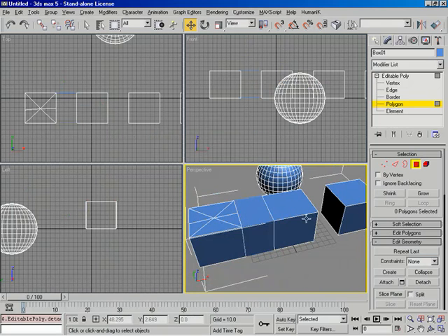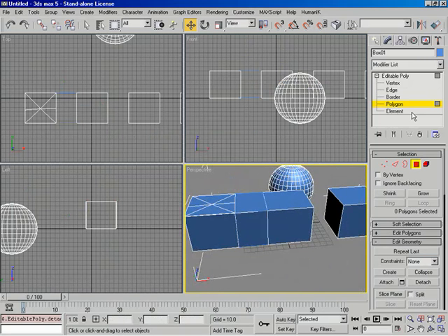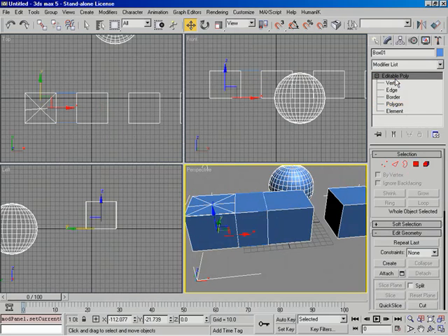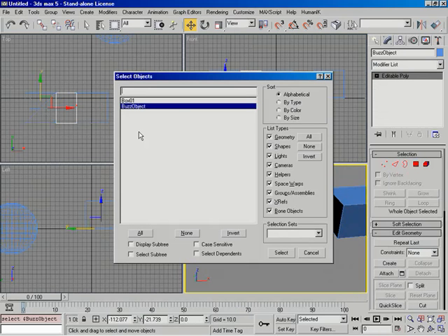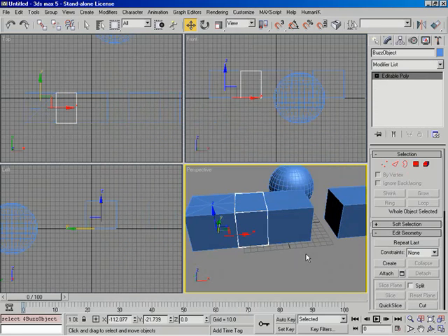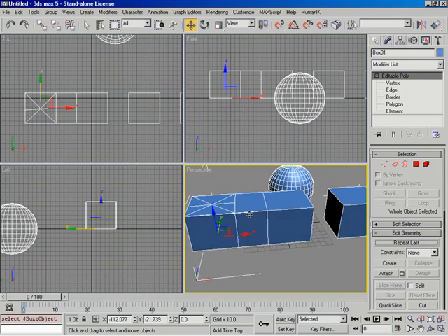So now you'll notice that as I start to rotate around it, he's no longer highlighted white. It's because I'm still in subobject mode with the original geometry selected. Let's go ahead and come out of subobject mode and click. And now we've got Buzz Object selected. And if we open up the Select Objects dialog, you can see there are two objects. So he now actually exists as a separate object. Exactly. So, very, very handy. All right, so let's go ahead and undo. I'm just going to come up here and right-click on undo and go all the way back to the point that I did the detach. So now we've got everything put back together.